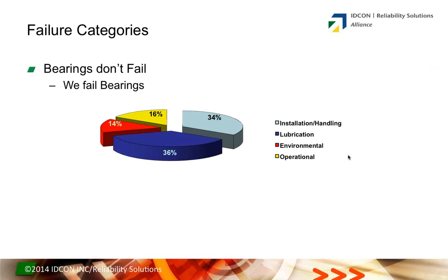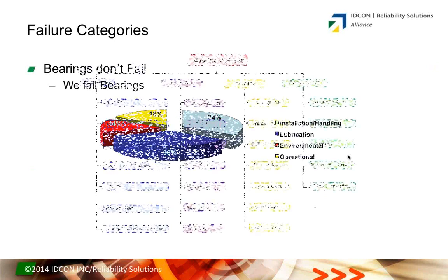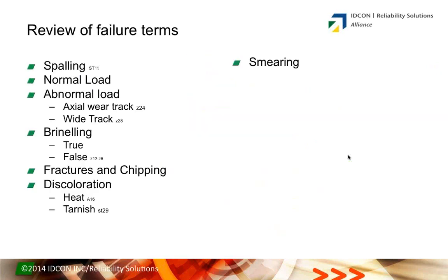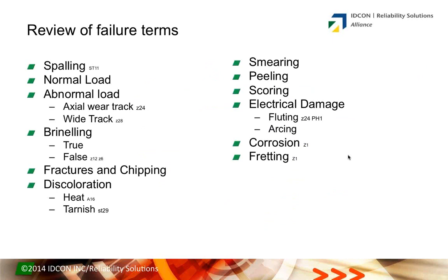So, talking about bearing failures, there's a lot of terms available that we use around the failing of bearings, and probably one of the most common here is spalling. When I see bearing failure reports saying the bearing failed due to spalling, it's really like, tell me something I don't already know, because the reality is that just about 99% of all bearing failures, no matter what happens, will all end up at spalling.